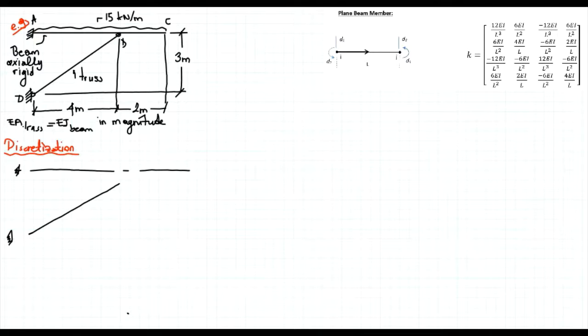Now, regarding this cantilever, remember that it doesn't matter how much deflection we get at the end of this cantilever. The end forces should always be the same, because within itself it's a determinate structure. So all end forces are known. If I know all the end forces, I don't have to worry about the deflections at this end, because it doesn't matter.